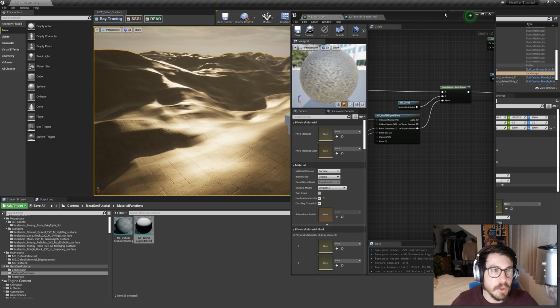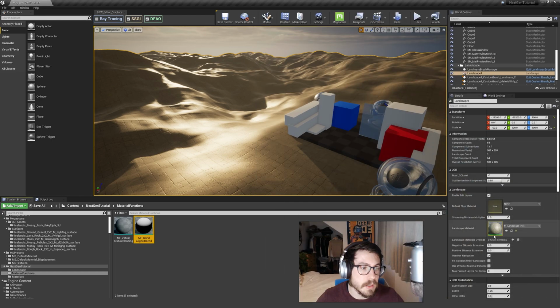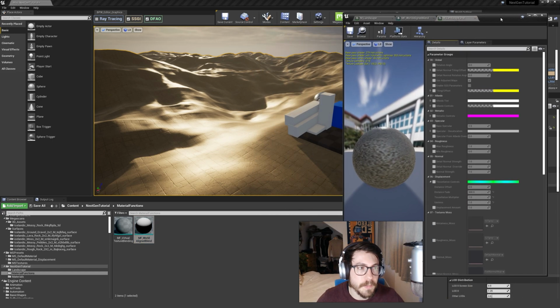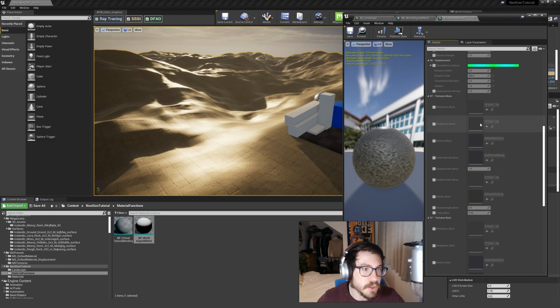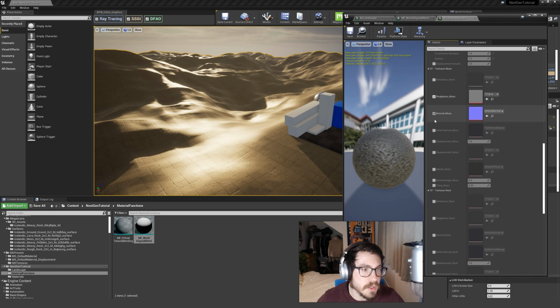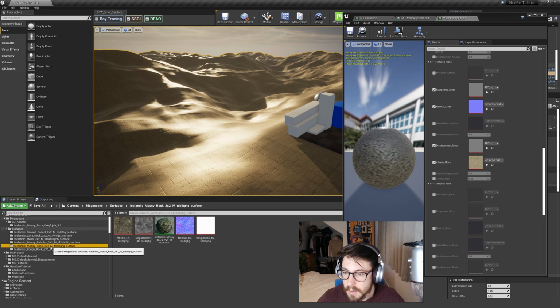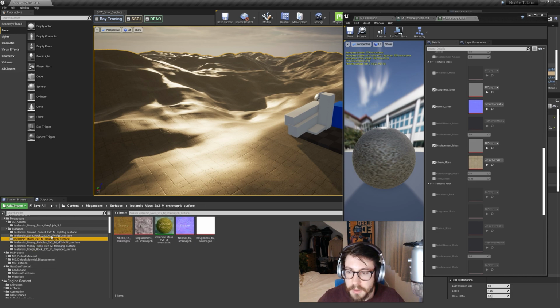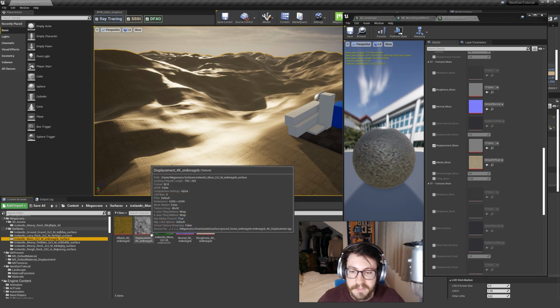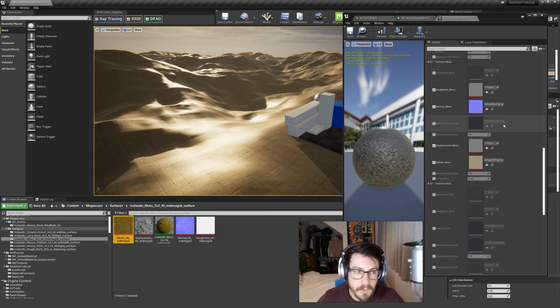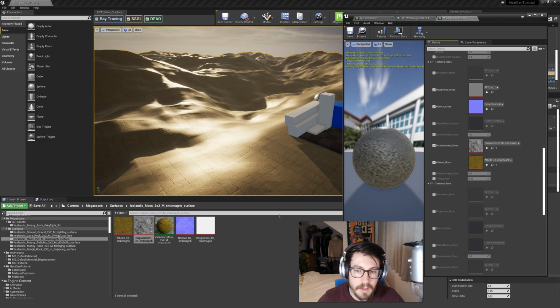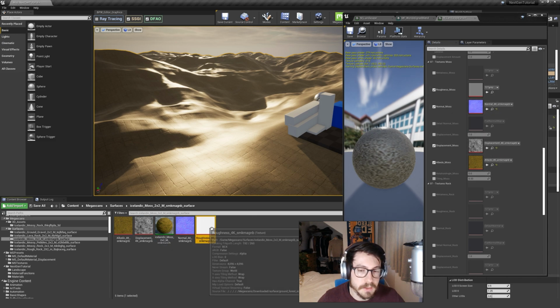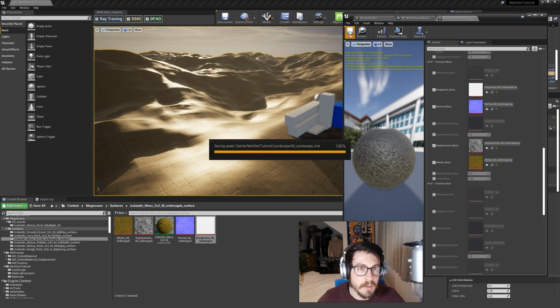So we will need to open our material instance. Here we go. And then assign the right textures. So for our moss material, metalness we need roughness, normal, displacement, and albedo. I'm just going to choose the moss material that I exported over, this really vibrant one. I like it. Just assign the correct textures. This is the height map. This is normal. Save that.